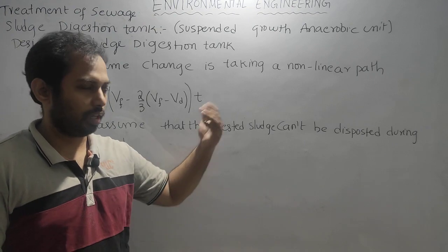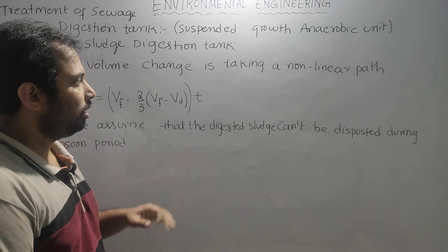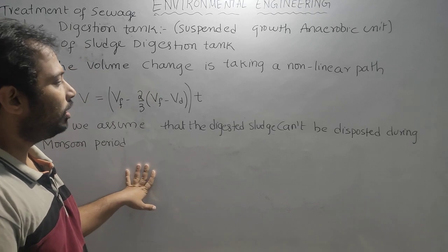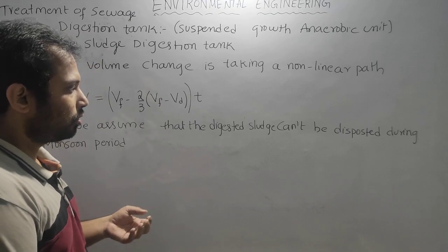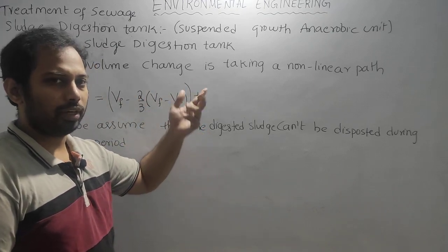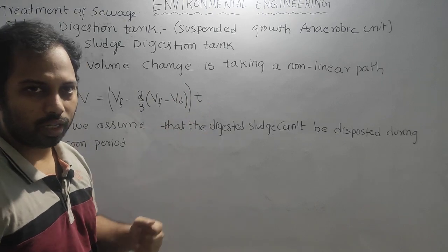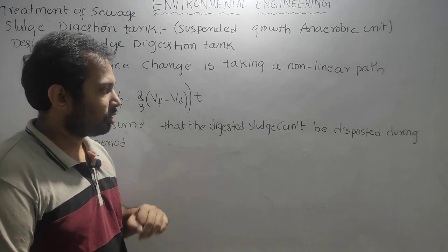That is the next step of taking care of the sewage. Here, digested sludge disposal is needed. Whatever gases come during the digestion will be trapped. Whatever supernatant liquor comes will be sent back into the system because its BOD is in the range of 3000 ppm.